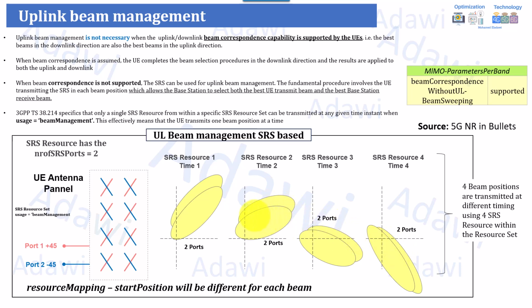But the most important part is that the gNB must assign a unique SRS resource identity to each of them, to ensure the later feedback from the BTS is not ambiguous when the gNB signals back the best beam out of these 4. Each one will have a unique identity.